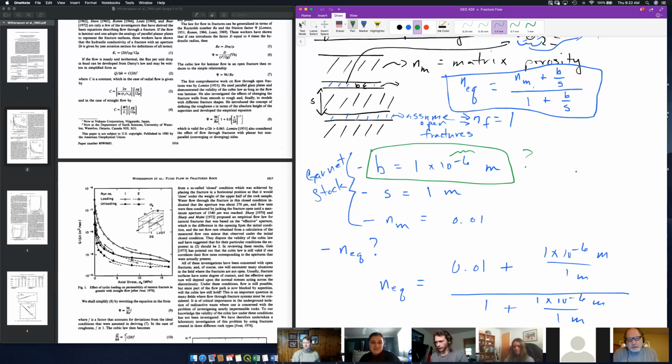Did you get it from first determining the conductivity of? Aha! So Kf equals rho water, g, b squared over 12 mu. If I can measure this, then I can get this. So this is often how we try, and you've got to get crazy to try and back this thing out. But generally, we do it in this manner.